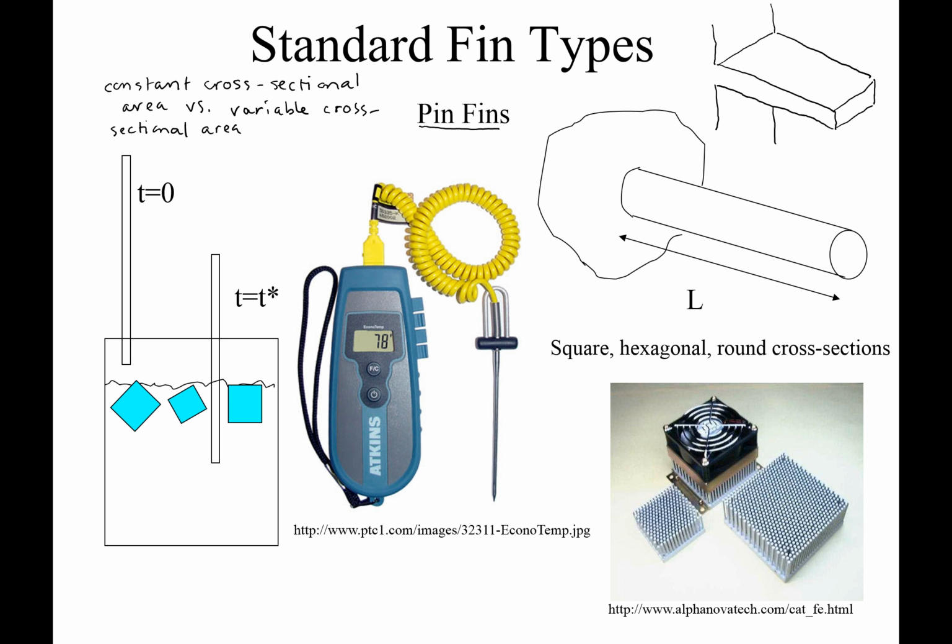And I point out that the pin fin is an approximation for, for example, a temperature measurement device. It might be, for example, a thermocouple type device or a thermistor type device. So you might have a temperature measurement device where the detector, for example, could be at the tip, but the elements of the construction allow for heat transfer and conduction to occur all along the axis.